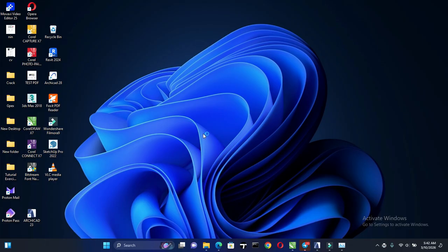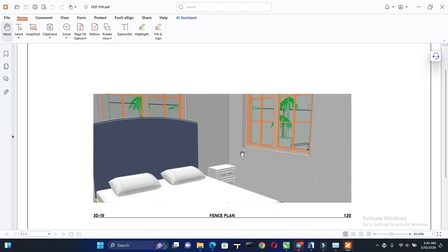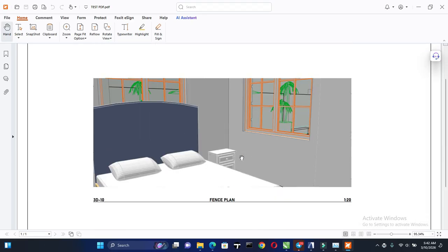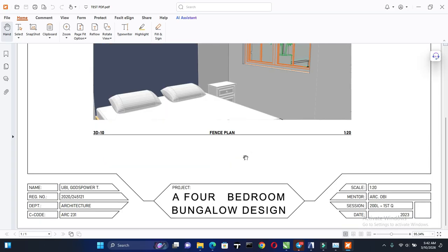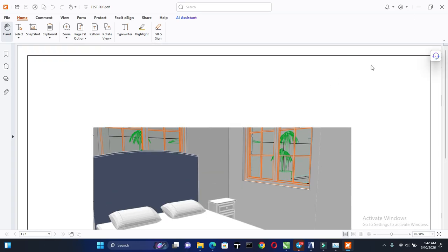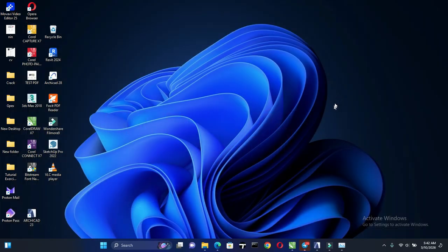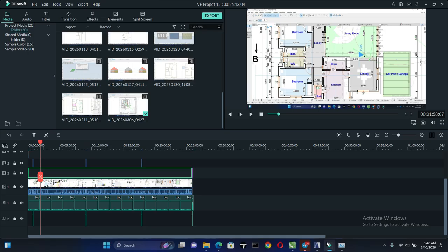So this is where you create new lines, this is where you change your pens. As you can see, we have 03 Architectural something. So 03 Architectural, that's the pen set we are using. If you want to alter any pen here in 03 Architectural 100, it's going to reflect in the pen set you are using. But if you don't like 03 Architectural and you want to use Building Plans, you can also customize things and then update this.